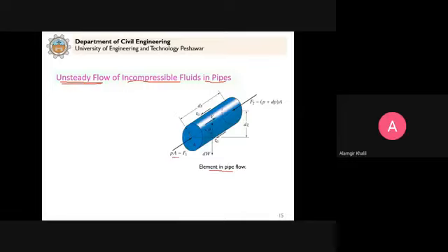So we have these two forces which are acting, F1 on this element here. The cross-sectional area is A, radius is R. This is pipe flow. So we consider cylindrical fluid element. Now F2 is P plus dP into A, differential change in pressure multiplied by this A. The vertical distance between the two ends of the element, that is denoted by dz.